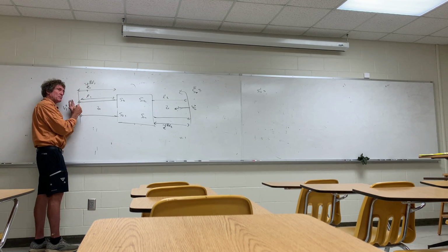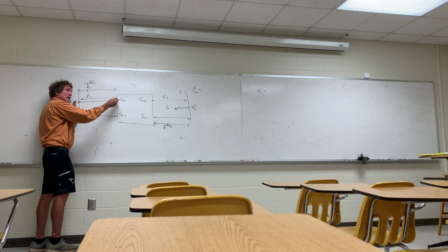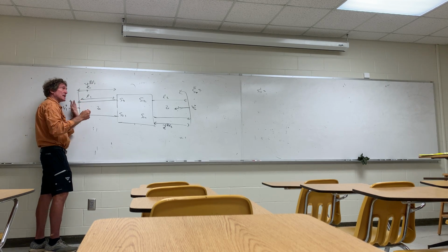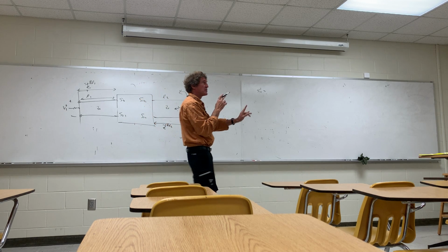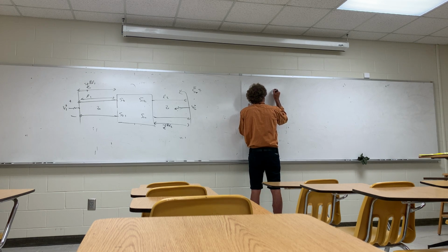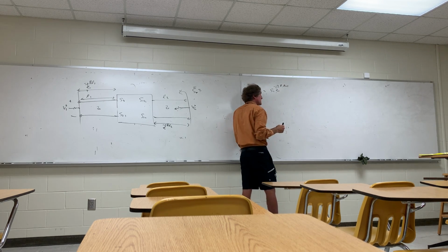All right, think of it. V1 plus now comes in here, goes down, so now there's a delay of e to the minus j beta L1 to this point. It hits, and the reflected field is going to be S11 times that, comes back over here, and so now the reflected field, my V1 minus right here, is going to be phase delayed by e to the minus j 2 beta L1. So this really is: S11 prime is going to be the original S11 times e to the minus j 2 beta L1. That makes sense to everybody?